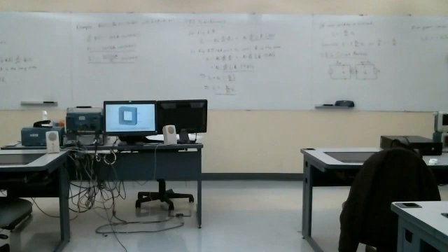But with I2 as shown, I need this minus sign to represent the power being absorbed by the load. Now this equation assumes that the transformer doesn't use any power itself. That's not quite true. Any practical transformer, due to the resistivity in the coils, will convert some of the input electrical energy to heat. So transformers aren't 100% efficient. But this assumes that they are, so this is for the ideal transformer case.